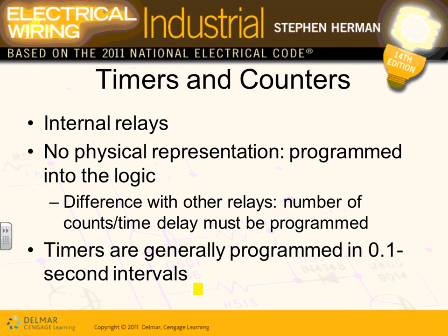Okay, timers and counters. Same thing. Timers and counters, guys, are all internal relays. No physical presence for these timers. They don't exist. They're in the memory, in the logic. The difference with other relays is that the number of counts and time delays must be programmed. All these, the timers and the counts, are all programmed, so they don't exist outside the system. And their timers go in increments of 0.1 seconds for the most part.